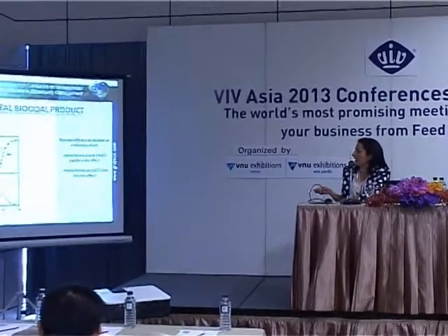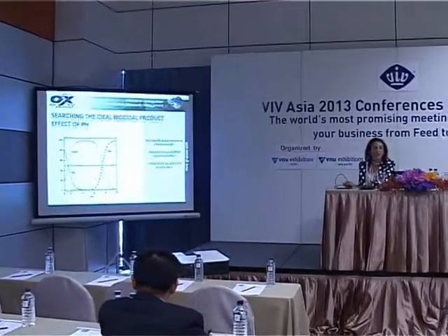If we explain a little bit more about these chemical and physical parameters, you will see the differences, or why I say that hydrogen peroxide and peracetic acid is the only one which is effective, even in those difficult conditions. If we study the effect of pH, for example, when we use chlorine for water disinfection, pH of water is very important. Depending on the pH, chlorine forms or decomposes in hypochlorous acid or hypochlorite ion.